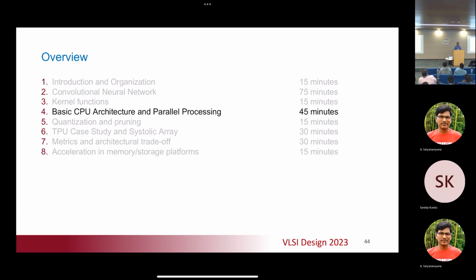And Microsoft was an interesting case because they came up with a number called MiniFloat, and that MiniFloat has something like a 5 or 6 bit exponent and only a 2 or 3 bit mantissa. And they're using that in their FPGA hardware. Because in an FPGA, if you want to do a 16-bit operation, the number of cells you'll end up using will explode. So they try to pack that into an 8-bit or 9-bit floating point number because they're using FPGA for computation.